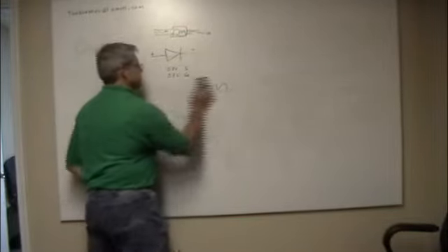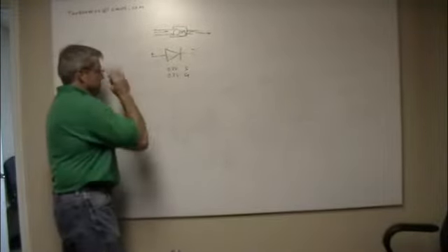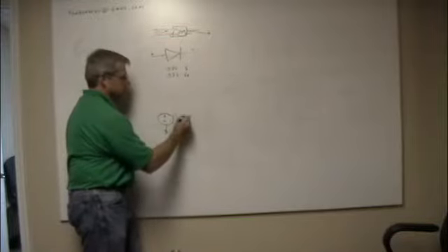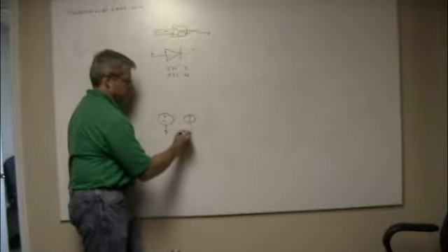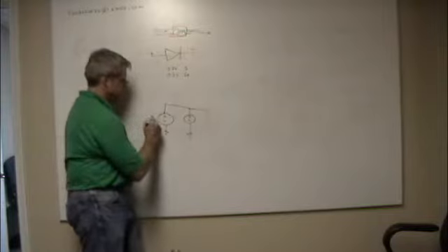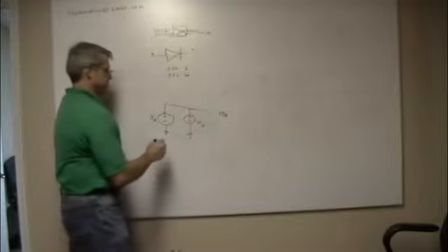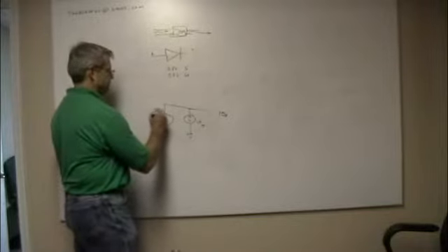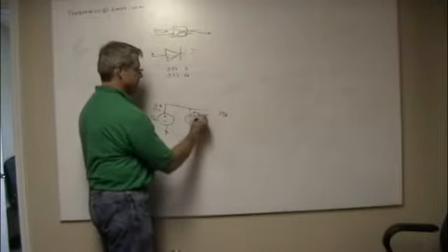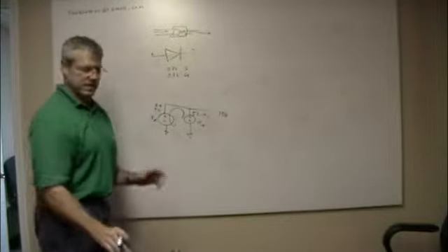The last thing that I personally use a standard diode for is we talked about originally if you've got 2 power supplies. Don't ever do that to them, because this is a 5 amp supply and this is a 5 amp supply and I need 10 amps out here, because the truth is this 5 volt supply and this 5 volt supply is really like a 4.9 and a 5.1. And so that means current's going to flow like that. I'm just going to blow things up and it's not good.